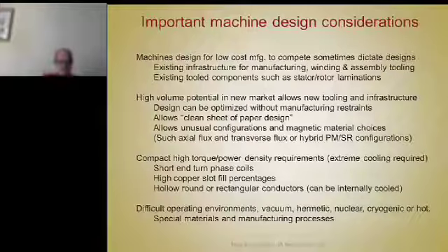Larger machines have to have channels through the cores for cooling, because the thermal diffusion paths are so long that the sources of heat are such a long way from the place where the heat can be extracted that the copper will heat up before it ever transmits this heat by conduction through the mechanical parts out where it can be extracted.